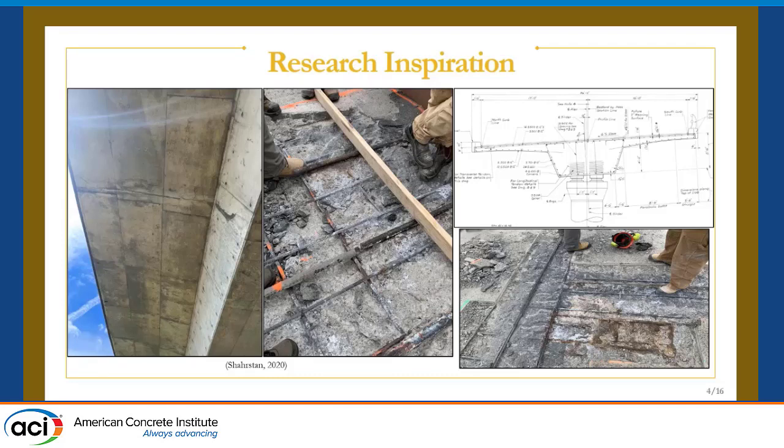And these are some photos I want to show you of the fruition of my thesis: there's a lot of degradation of the steel tendons. As I can show you on the second photo here, what was supposed to be 1.25" Dywidag pre-stressing bars at 2 feet on center, you see no duct, you see no grout, because it's supposed to be a bonded system, and you actually see some of the tendons snapped when we were performing some partial depth repair. So it was more dire than was necessary.